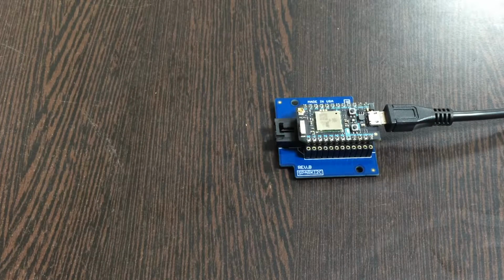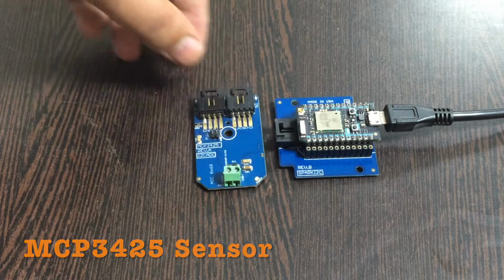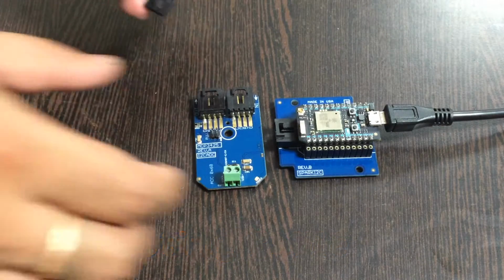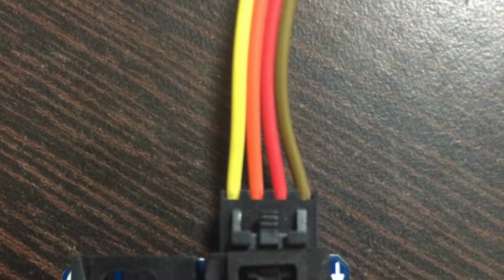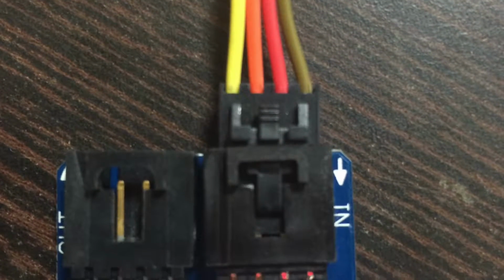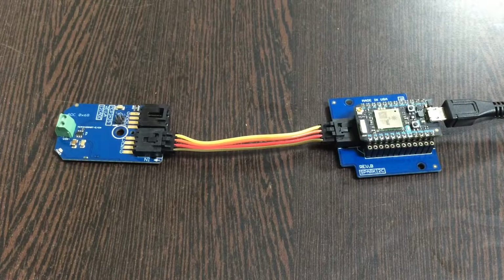Next, we require our analog to digital converter, that is MCP3425, and this here is a connecting cable. Now make the connection among the ADC and the cable, and make sure that the brown wire of the cable should be connected to the ground terminal of the analog to digital converter, and similarly to the ground of the I2C Shield. Now we are done with all the connections for this hardware. Now let's have a look over the code.